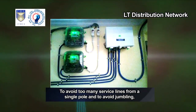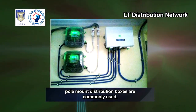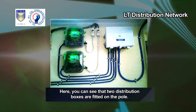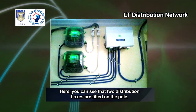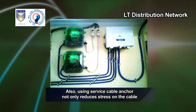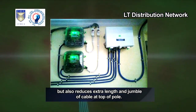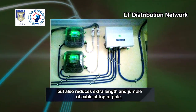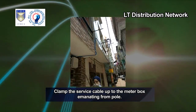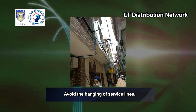To avoid many service lines from a single pole and to avoid jumbling, pole mount distribution boxes are commonly used. Here you can see that 2 distribution boxes are fitted on the pole. Also, using service cable anchor not only reduces stress on the cable but also reduces extra length and jumble of cable at top of pole. Clamp the service cable up to the meter box emanating from pole. Avoid the hanging of service lines.